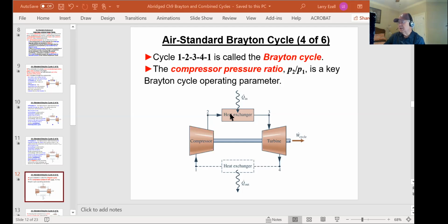It would be constant at 12 bar through the heat exchanger, but it'd pick up a lot of temperature, then go through the turbine and create a lot of work, turning those turbine blades and turning the turbine shaft with some torque on it. About half the work goes to the compressor, half the work goes to the generator. Then you've got, coming out of here, the temperature is still quite hot in this air. That's why there's an opportunity here to use a heat exchanger to grab some of that heat for another process. We'll talk about that later.